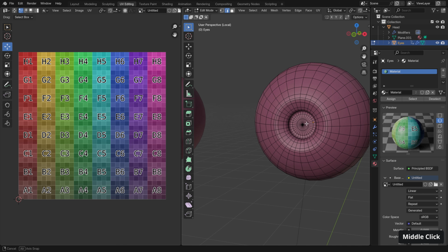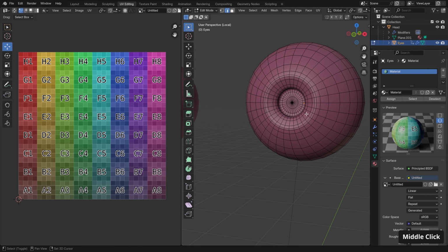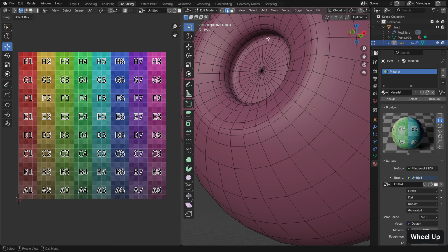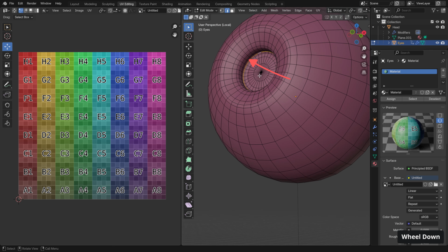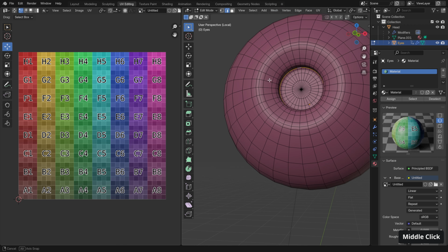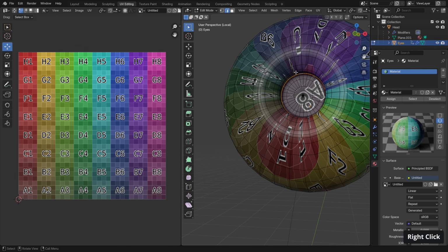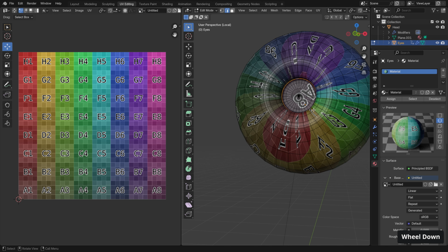Now, another thing to consider is that the inside of the eye here is basically going inwards, so this will be a cause of stretching. So we'd like to relieve some of that stretching here as well. The easiest way of doing this is just to go in here and cut out the flat part at the back here, so we allow this inner part to fold inwards. So let's go ahead and add in a seam to that. Now right away, the inside looks nice and clean, but the rest looks really stretched. So why is this? Well, let's have a look.